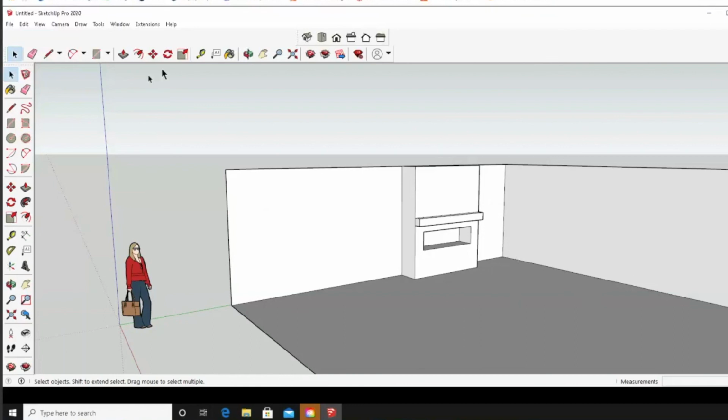So let's go ahead and do our guideline. It'll snap in the corner. Click, drag, lift up my finger, click, lift up my finger, drag along the edge so I'm staying nice and plumb, and I'm going to type in either 48 or 4 feet. So there's my measuring line. Then I'm going to click, release, pull up. I'm on the blue plane.